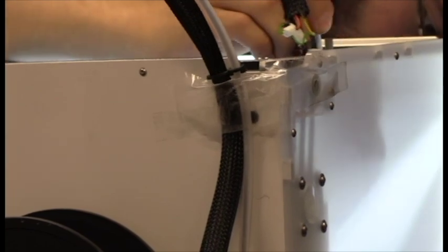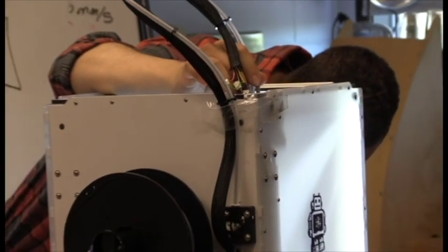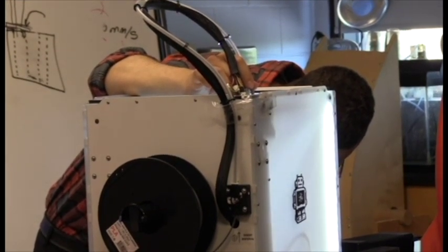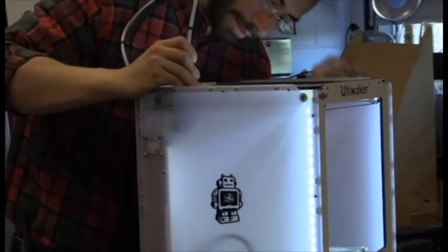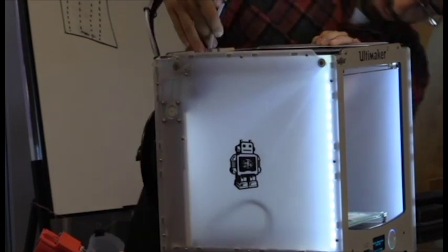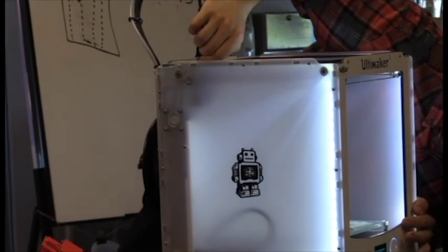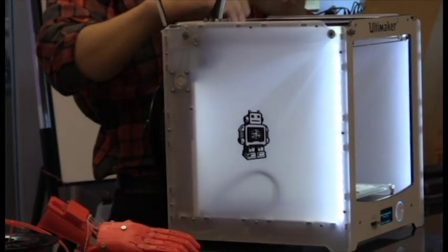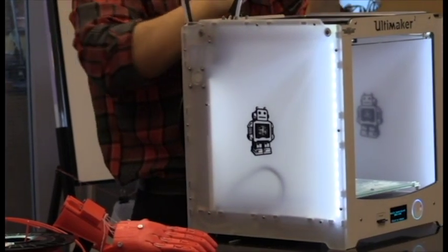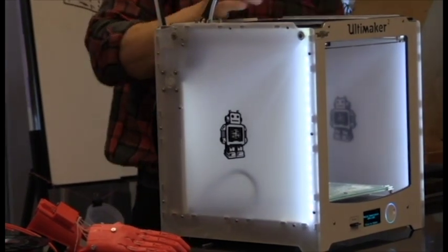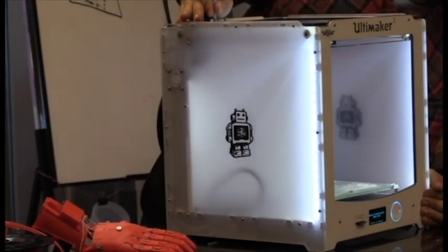And then I'm going to go to settings real quick. Material. Settings. Can you guys see that as I'm pushing down, stuff is coming up, or no? Okay. It's heating up. It's at about 190. Usually 190 is where it begins to solidify. 200 is kind of liquid-ish. 210 is kind of the sweet spot. 220 is where you want to be, completely fluid.